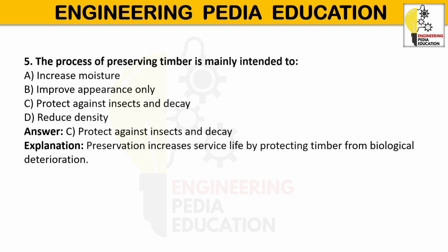Methods of timber preservation: surface application, dipping or soaking, pressure treatment, charring. And what are the common preservatives used? Creosote oil, copper based preservative, borate compound, water based preservative formula used for structural wood.